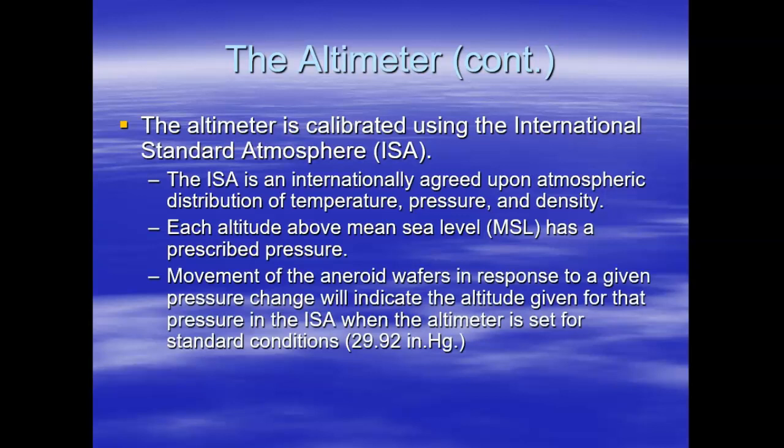Movement of the aneroid wafer in response to the pressure inside of the instrument will indicate the altitude given for that pressure in the International Standard Atmosphere when the altimeter is set for standard conditions at 29.92 inches of mercury.